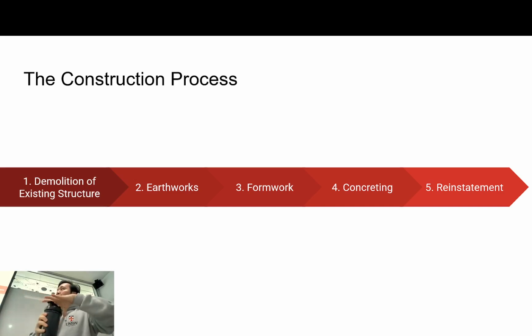some of the considerations for this, we need to think about things like site access. We also need to think about traffic. These are some things that you need to do that you actually won't learn about in this course, right? So I haven't really put that in there because I feel like it's not that important for you to understand. But when you do get into a job, that's where your engineering skills come from, right? You need to think about, okay, well, if this is on a main road, can I actually do it during the day, right? Because if you have to block off half the lanes just to be able to complete your works, it's probably not good during peak hour traffic, right? So you might have to resort to night works, other things, right?